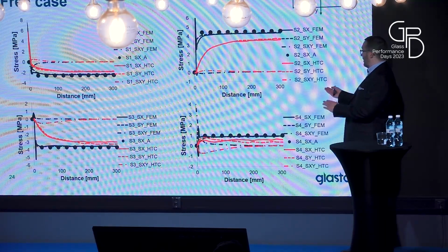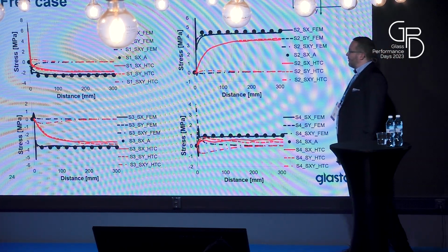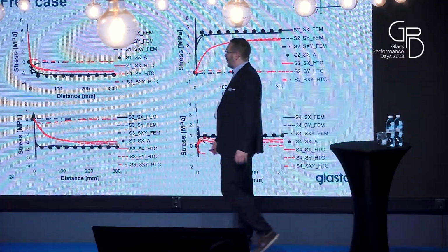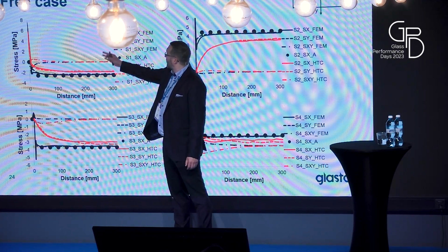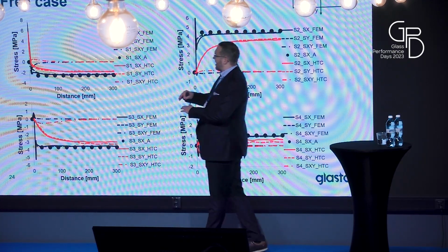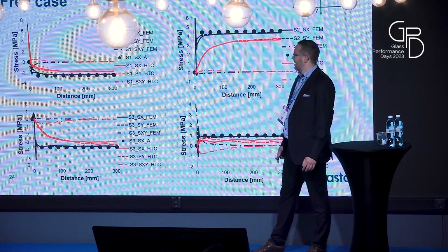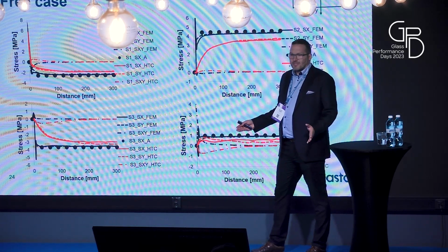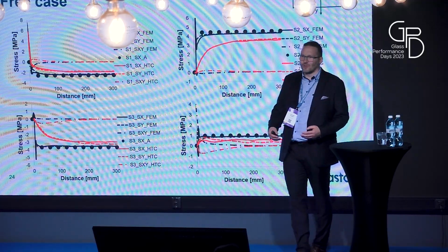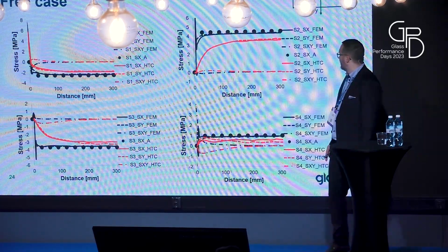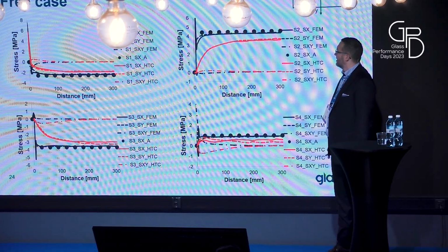And now, with red color, I have tried to show you what happens when we include this non-uniformity in temperatures. Like in the surfaces 1 for the free case, stresses are getting a little bit closer to 0. So that means that when we have uniform temperatures, we have an extreme case, and this analytical solution gives results for the extreme case. There are also other surfaces, other stresses.